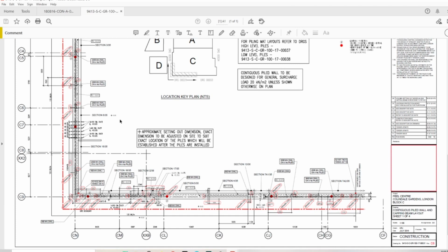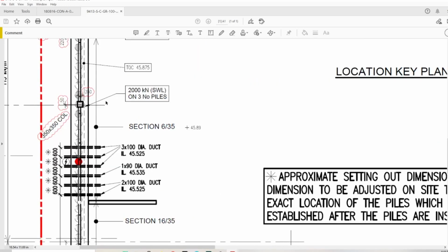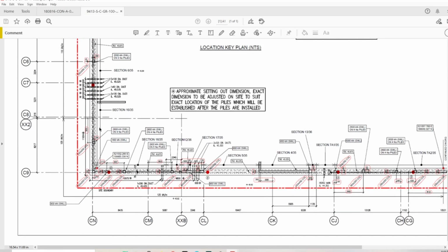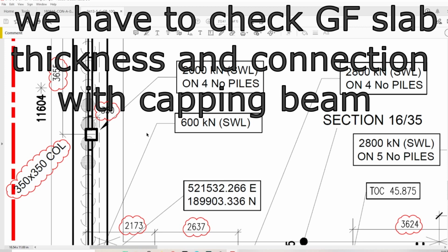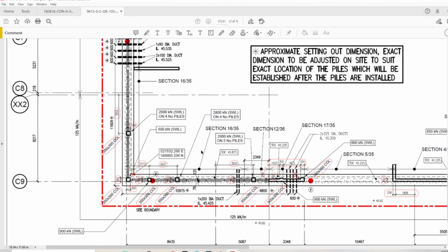So this designer shows you this way. As I said, this is very interesting: 2 designers, 2 ways of showing the drawing. In this case, since we have columns here as well, we don't actually need the ground floor drawing, because all the information is here. Obviously we're going to double check if these drawings correspond with the ground floor drawing and which one is the latest, just to confirm which one we're going to use for the setting out of the columns.